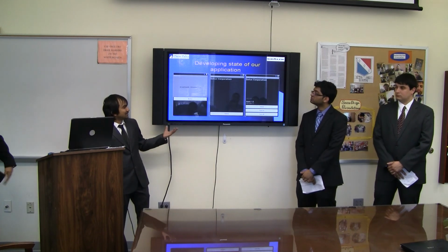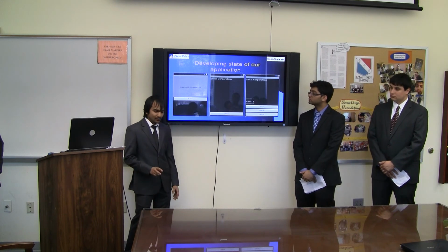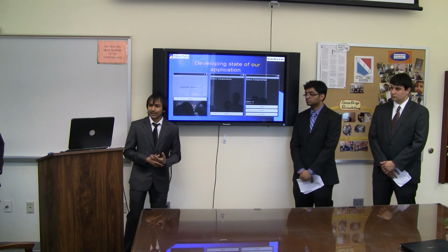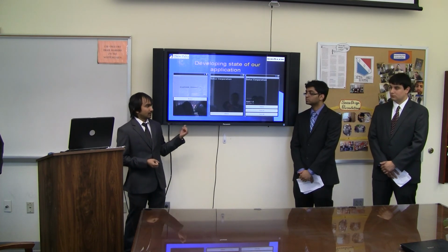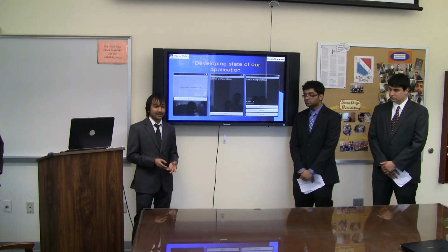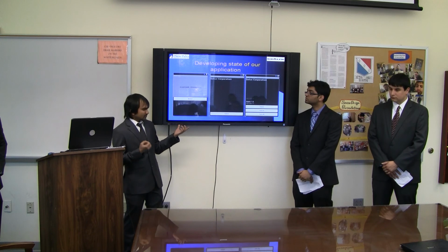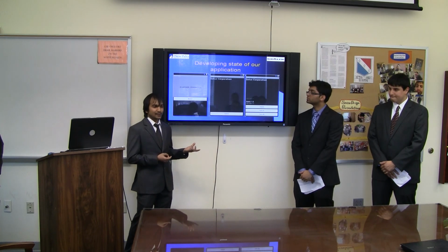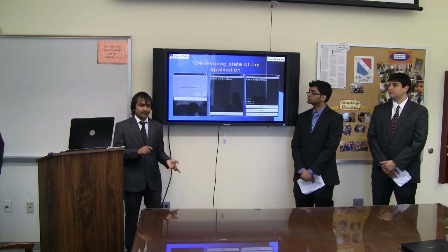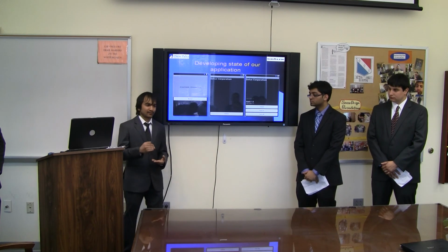Now there are some basic steps we followed when we developed our Android application. The first step was just to receive from our microcontroller, because that was the first requirement: whenever the light intensity of the LED module goes below 70%, it transmits the data and lets the user know. So our first aim was to create a button that sends data to the microcontroller, and after receiving the data from the Android application, the microcontroller transmits whether it went below 70% or is still above 70% or 50%.